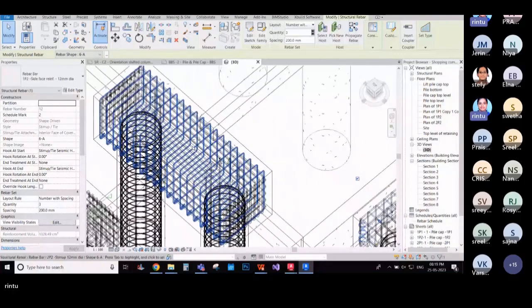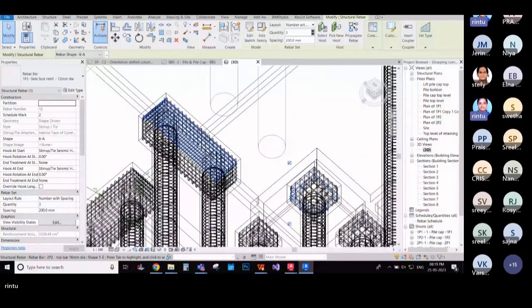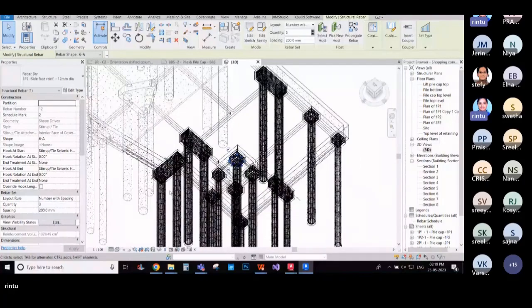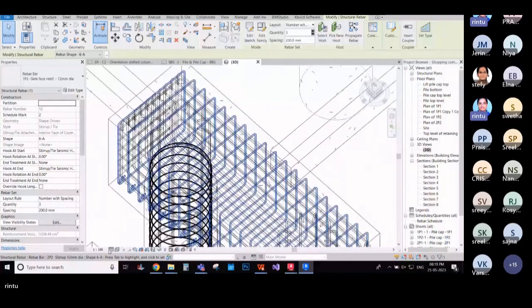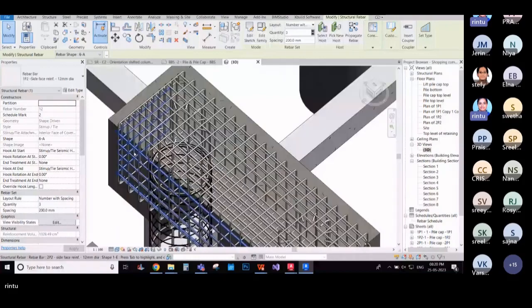So I suppose I'm clear to you regarding the main purpose of bar bending schedule. The main purpose is just simple. You will have to make a schedule which helps provide the reinforcement correctly so that it carries the load, and secondly, it can be easily implemented on site. These two are the main purpose and main focus of every engineer who works with a bar bending schedule.